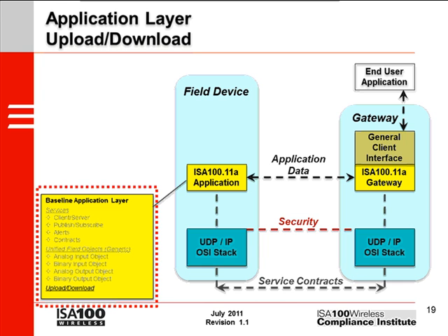So, that was a quick tour of the ISA100 application layer, which is sometimes called the native application layer. It provides some generic services that can be used to report a wide variety of data in a very flexible way. Thanks, Jay. So what we've seen here is just a quick summary of the ISA100.11a application layer. I guess the main point here is that the ISA100.11a standard provides a complete framework for reporting process data, roughly corresponding to the 4-20 milliamp level of capability.